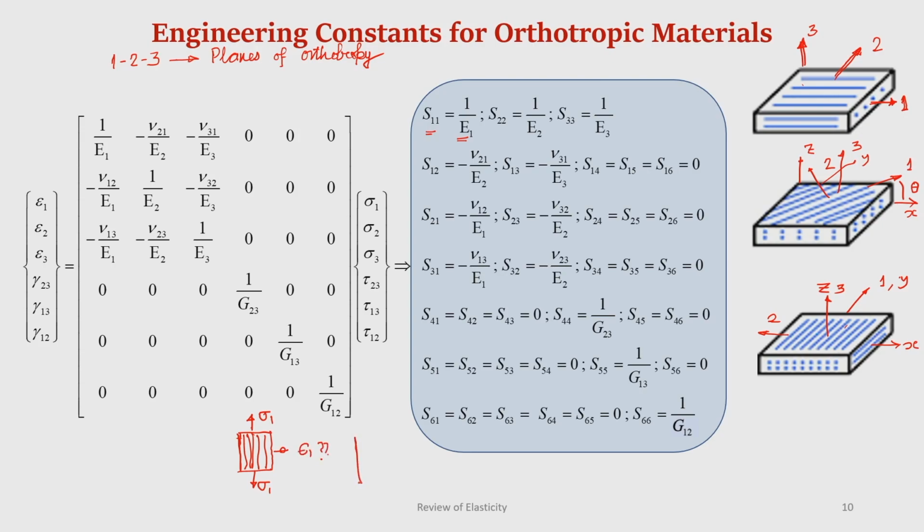From the stress strain curve and the strain gauge reading you get epsilon 1. So, you can find out E 1. Similarly, by loading along direction 2 we can get E 2, and hence we can get all of these. Even the Poisson's ratios could be calculated, but make sure that the relationship between Young's modulus and Poisson's ratio which we knew for isotropic material actually does not hold good here. Okay.